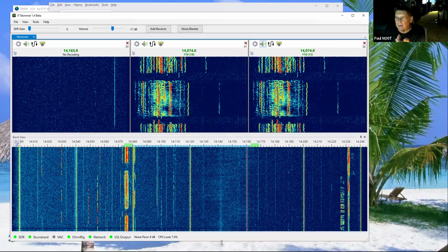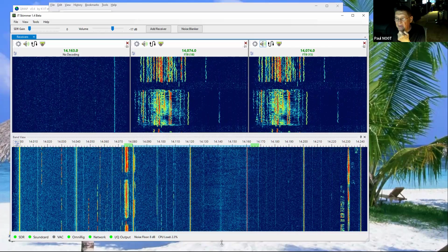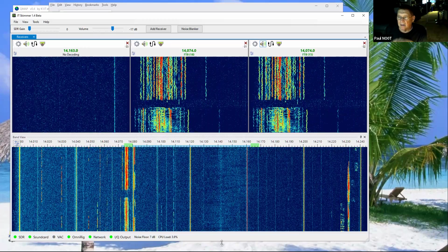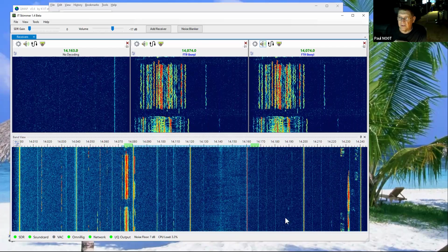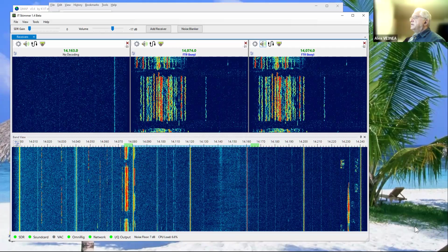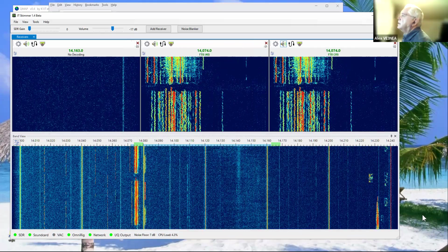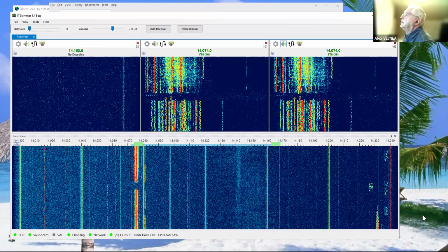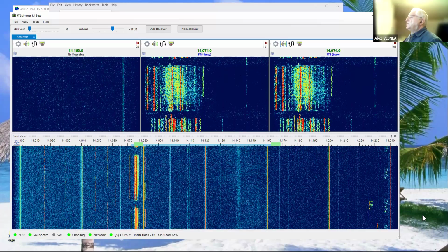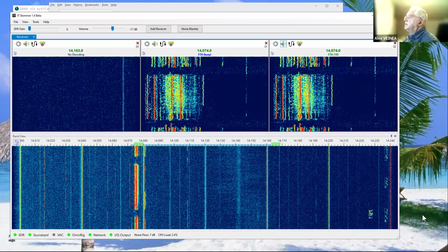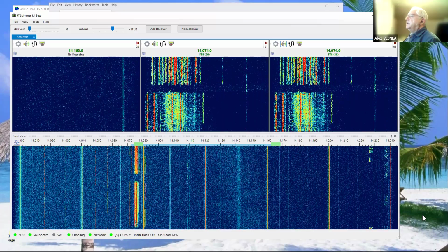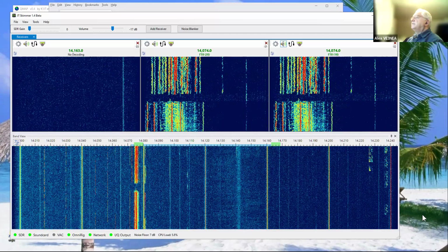The AirSpy Mini versus the AirSpy R2. The Mini is kind of a lower cost version of the R2. Yes, yes. It doesn't have some extra features, like it doesn't have extra in-out bits that you cannot use anyway without writing custom software. Gotcha. It doesn't allow you to discipline the oscillator, but that's what I'm not using anyway. So for me, Mini is more cost effective.